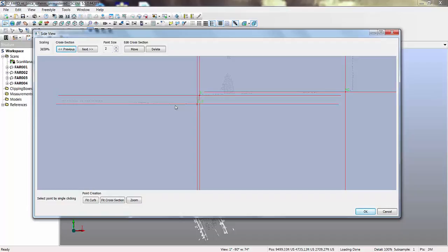I'm looking at dozens of points to determine what that correct low point should be, and I have a better viewpoint of this looking at it from a cross-section as opposed to standing out there on the side of the road looking at this. In my professional opinion, I think we're going to be at least as accurate as a crew collecting this with conventional methods, but realistically I believe we're getting a more accurate representation of these features.